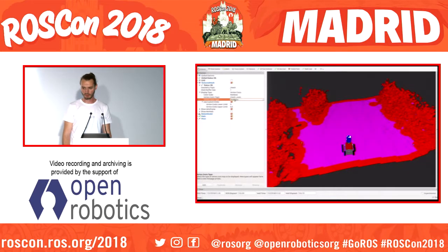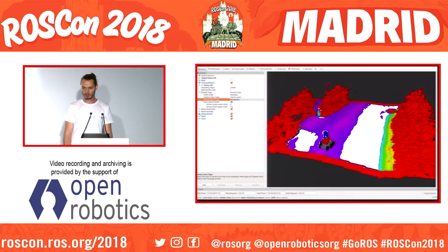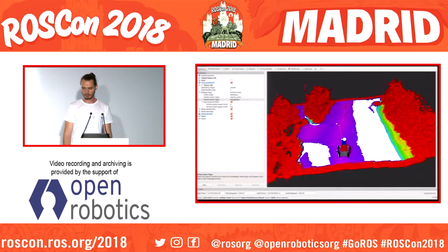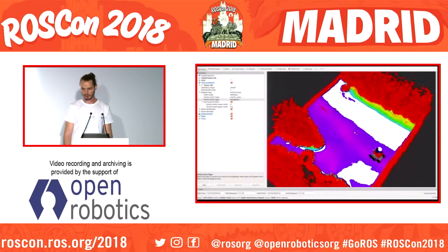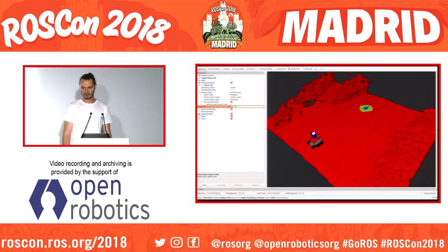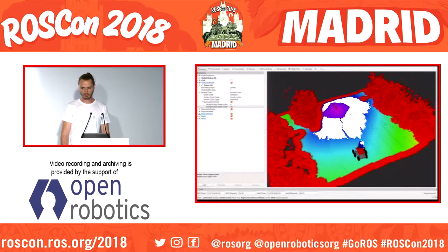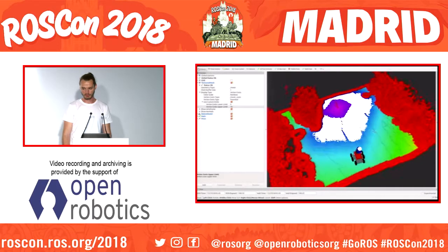So we can perform then path planning and navigation on that. So also we provide a tool for selecting a pose on the surface of the mesh, and then move-base-flex got that pose and is computing a path. And we also can then display the potential field for that. And you can imagine like a local planner or a controller is using that potential field.